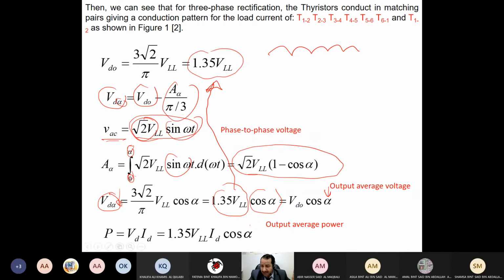Now this thyristor circuit is useful for many applications in industry. In industry, you know the machines, the ovens I mentioned before. If you have, as an example, a DC motor, you want to control it. It's part of the production process, food production, or ammonia or hydrogen production, or some chemical for cleaning, or let me say aluminium production, or whatever it is. You increase or decrease alpha, increase or decrease the voltage, increase or decrease the speed, and it reflects on the production. So increasing or reducing the speed through increasing or reducing the voltage, through increasing or reducing alpha, will reflect on the production.